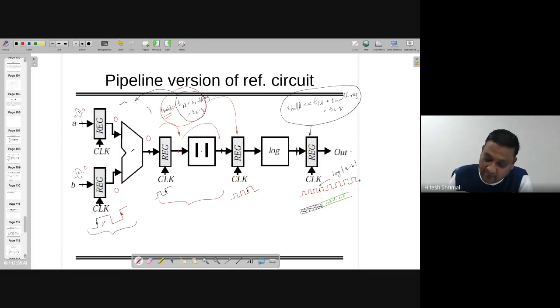The fifth clock is the one which is going to give you the next data. And again, it's continuous streaming, right? So this is what is happening, and every time this data has to be stored somewhere, otherwise it's going to be erased, right? Such a thing is known as the pipeline.